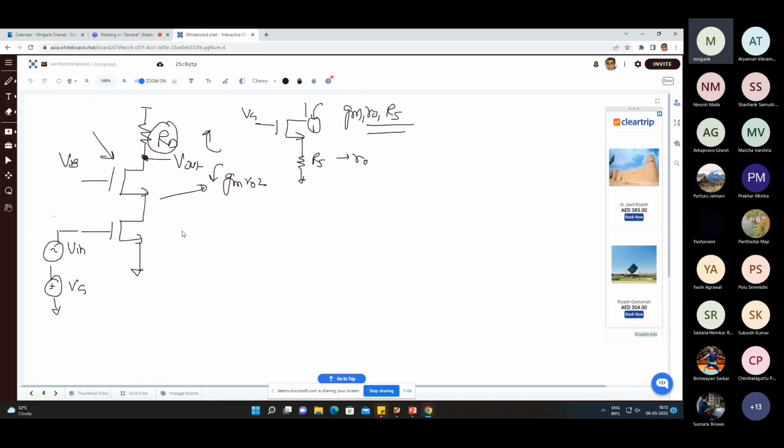So that is fine. Now if I want to find out the gain, what is the gain? Without even doing small signal analysis, how can I find out the gain? Can we conceptually find it out? Yes, the lower transistor is like M1, then we have the other method: the transconductance of the whole circuit, then you find the output resistance and you multiply. What do you mean by transconductance of the whole circuit?